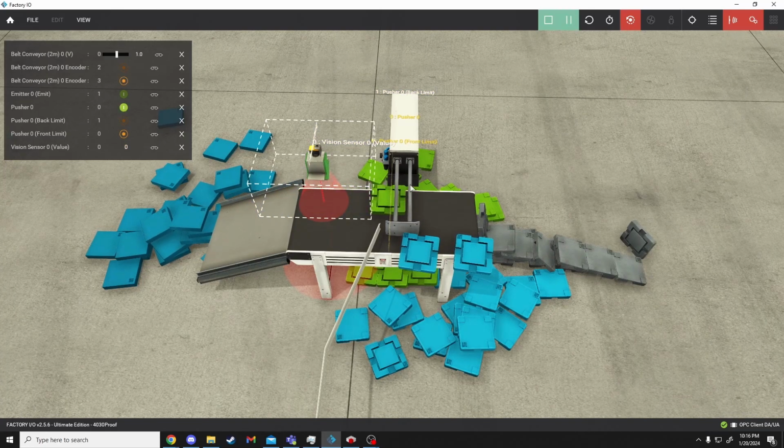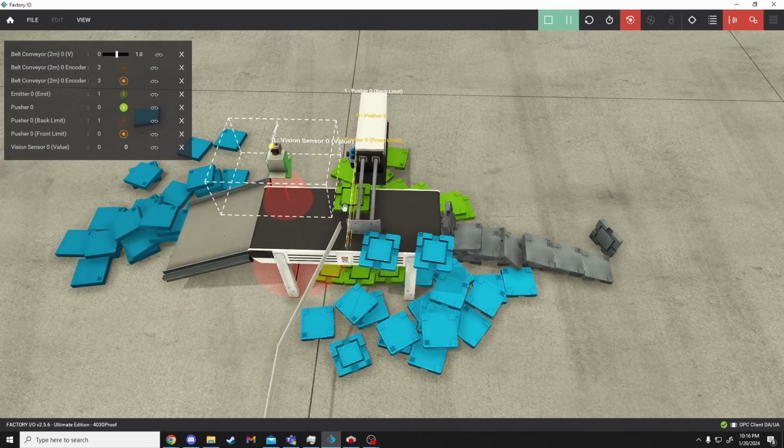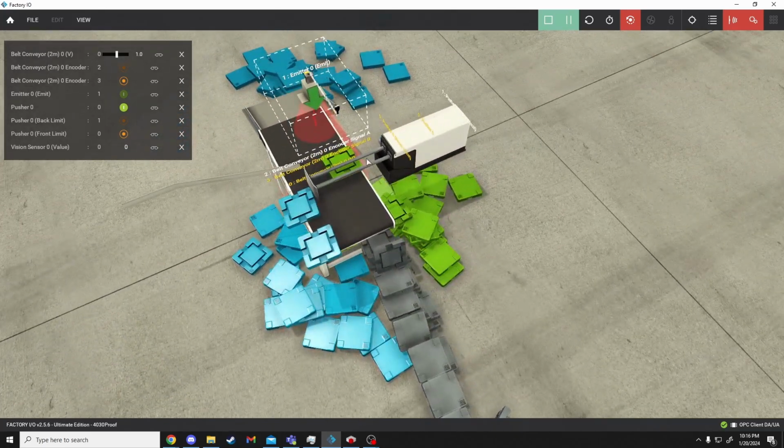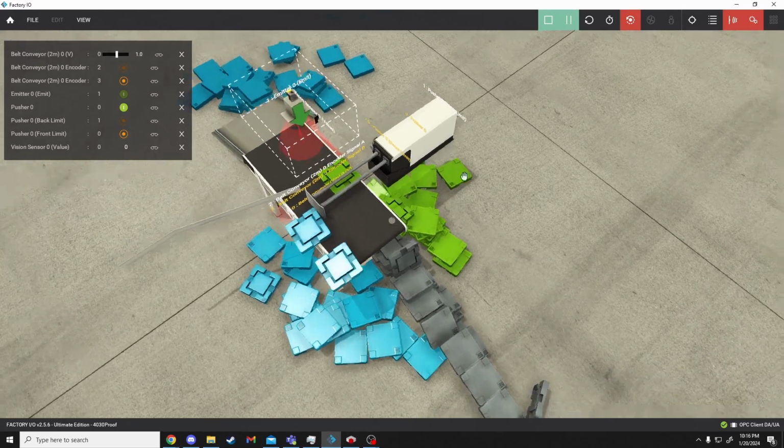For this green part here, let's pause real quick. The piston pre-extends once it determines that it is a green part. In our case, we're dealing with squares, triangles, circles, and the defect part is an octagon. But we'll imagine the green part is a square, we'll say. Once it's identified by the camera that this part is green or it's a square, whatever you want to think about it as, the piston pre-extends. And then we have a scraper blade that is going to pull the part off of the back of the conveyor belt to drop into whatever collecting bucket we have on that side of the conveyor.